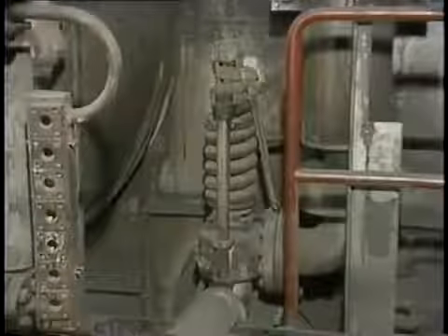To protect the boiler from overpressure, a special type of valve is installed in the superheater and reheater outlet lines and on the boiler drum on drum-type boilers. These special valves are called safety valves, and they protect the boiler from overpressure. Safety valves come in a number of shapes and sizes. Regardless of whether a safety valve is installed on a boiler drum or on a superheater or reheater, essentially safety valves all work the same way.